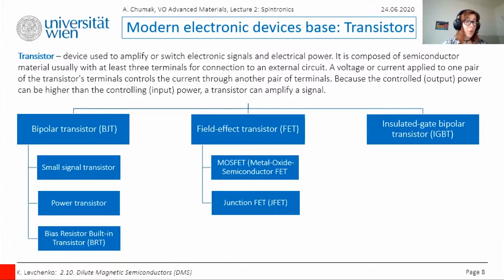In the case of a bipolar transistor, we may have a PNP or NPN configuration. In an NPN configuration, the flow of the majority carriers is from the emitter to the collector, and it forms the current flow in the transistor. The collector terminal is always connected to the positive voltage, while the emitter terminal is always connected to the negative supply.